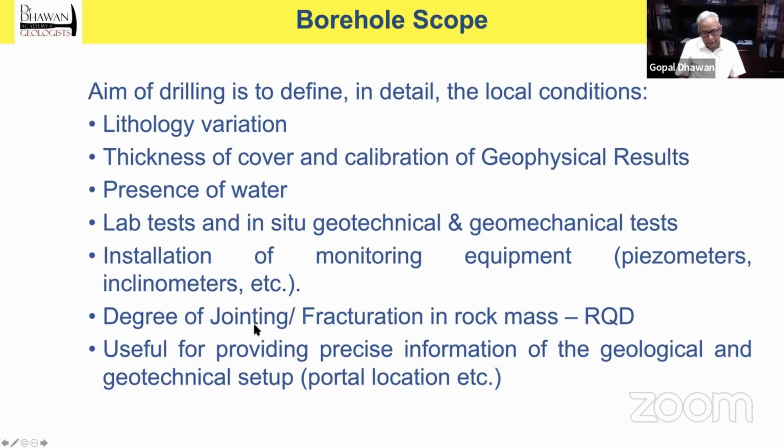Then the degree of jointing and fracturing, through which we calculate RQD, which is a very important parameter for assessment of the rock mass. And these are useful for providing precise information for the geology and geotechnical setup.